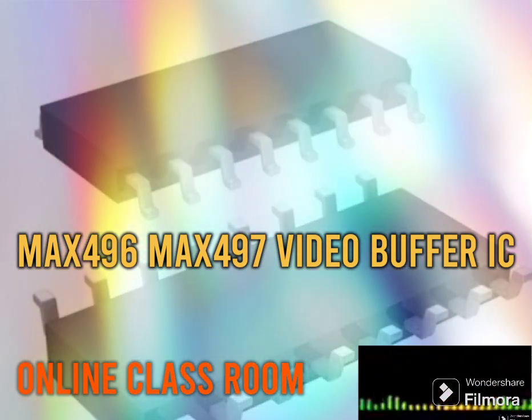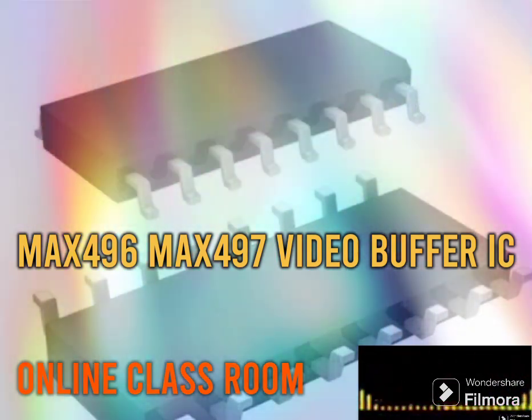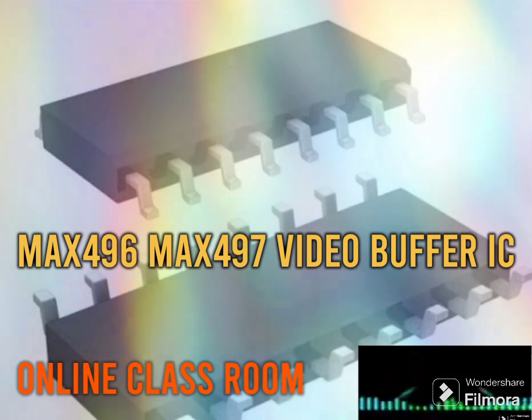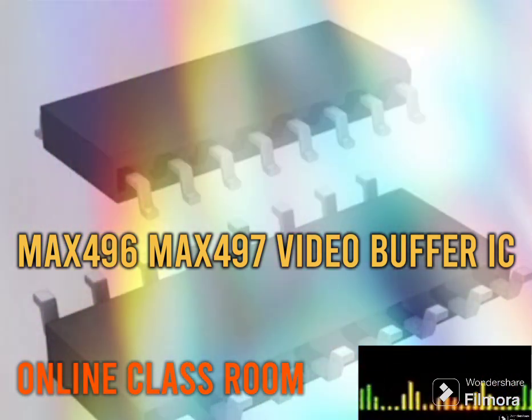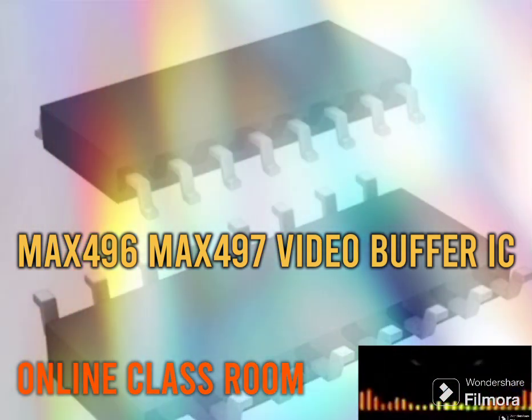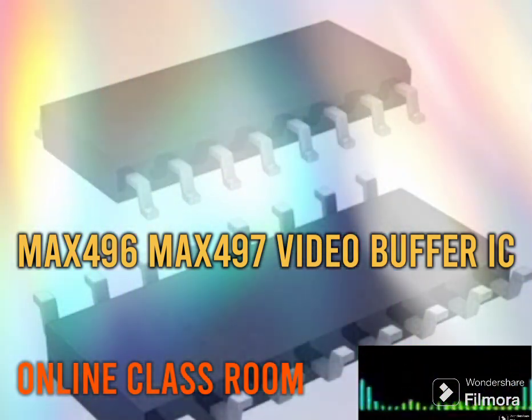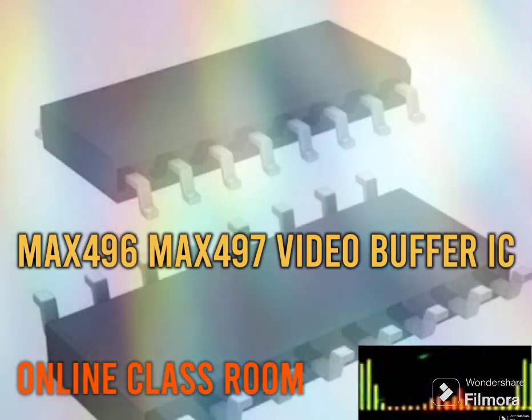The first stage of the amplifier is resistively loaded, which allows for low input referred noise even with low supply currents. It can drive 50 ohm or 75 ohm back terminated cables to plus or minus 2.8 volt and has low differential phase and gain errors. These amplifiers are suitable for demanding component and composite video applications.